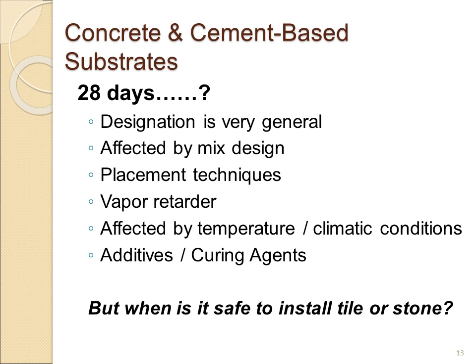Climatic conditions on a site can also affect how long a concrete slab is going to cure, and also the fact that HVAC is not turned on for an extended period of time, and you really don't know how much moisture is in that slab or in that groundwater below it.